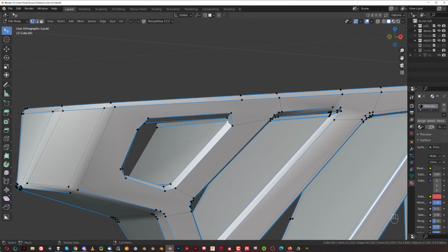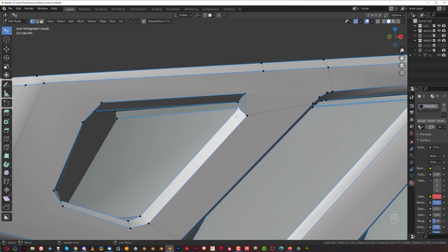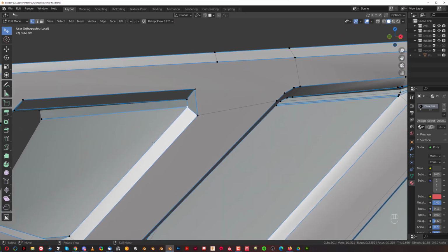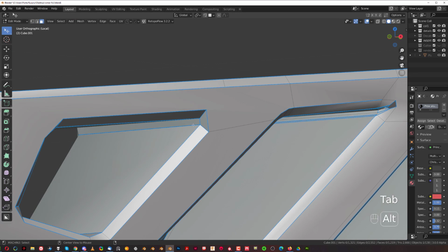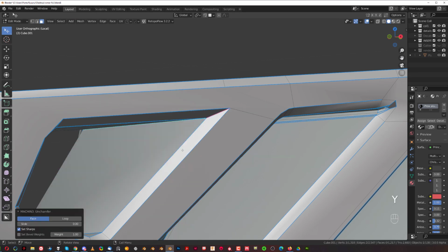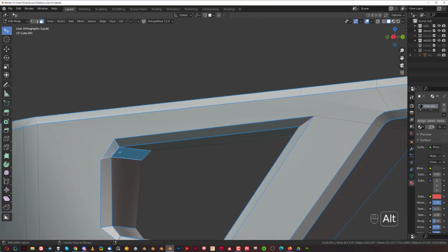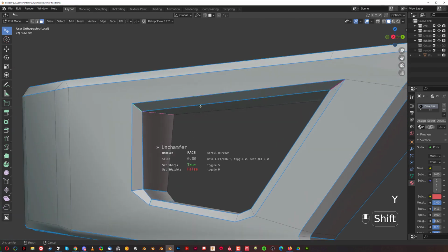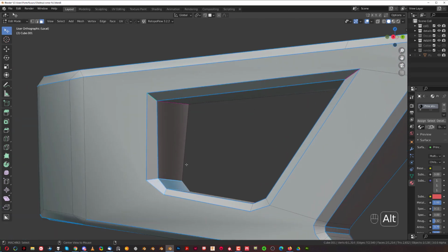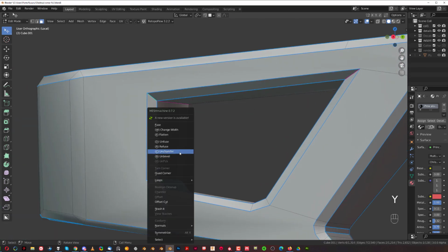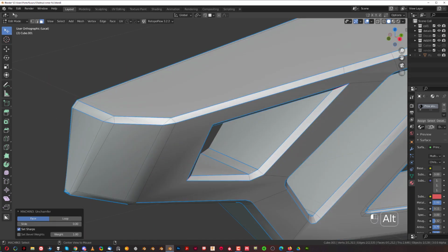Now, the way to clean these bevels, you need to remove the chamfers, and the only way to do this is by using Mesh Machine on chamfer. It's going to literally remove that thing, okay? But then later we're gonna have another situation which is gonna be quite interesting, which will not allow us to do it, because we're gonna have bevels running through